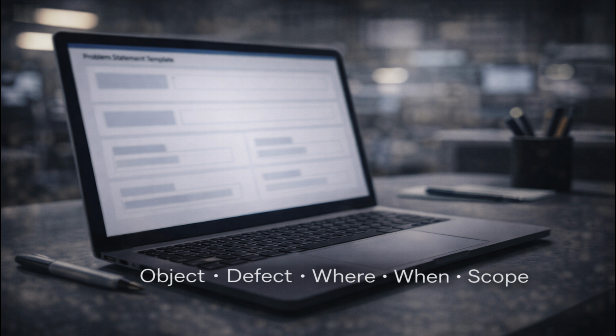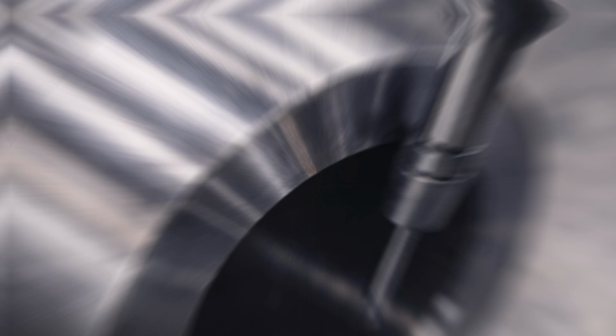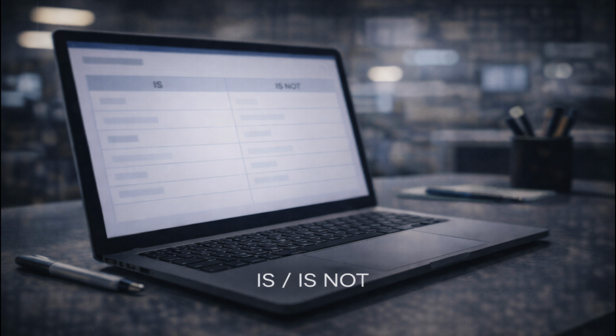How widespread is it? For example, the shaft hole must be 10 plus or minus 0.1 millimeters. Oversize measurements drifting to 10.48 to 10.52 millimeters have been observed on line B during the night shift since the third week of February at a frequency of 4 to 5%. Anyone who reads it should picture the same thing.